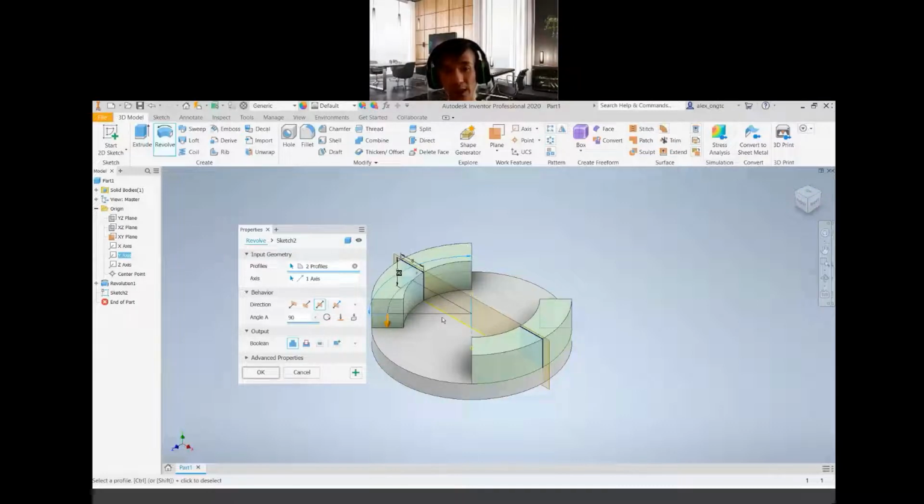Okay, so for the rest of you, please follow through. Go to select symmetric, and then for the angle put in 90°. So symmetric will be like this. It will divide equally.